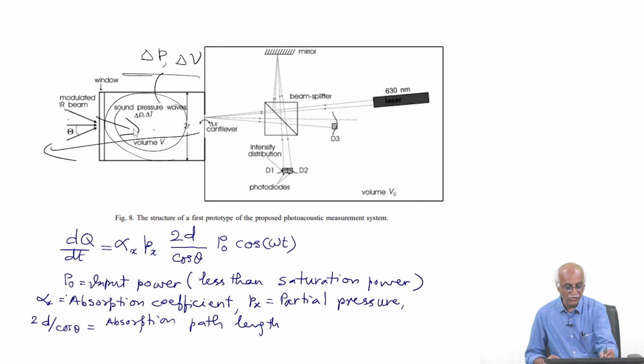These changes are captured using the cantilever beam deflection, and this deflection is captured using an interferometry approach. It can also be captured using a diaphragm type capacitor microphone, or based on the bending stress induced in the cantilever beam. However, for very small detection, the interferometry approach is very sensitive to phase change. So we can capture this information, which indirectly connects with the concentration change.